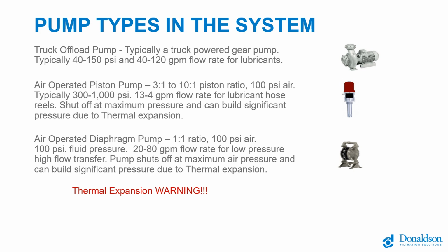If you have ever picked up a garden hose that has been sitting in the sun with the water shut off and noticed that it has a lot of pressure in it, that pressure did not come from the pressure in the water line. It came from heating of that garden hose in the sun. That's called thermal expansion. And that water wants to expand, and it's being constricted by the hose. And you pull the trigger and it squirts some water and the pressure drops away to nothing.